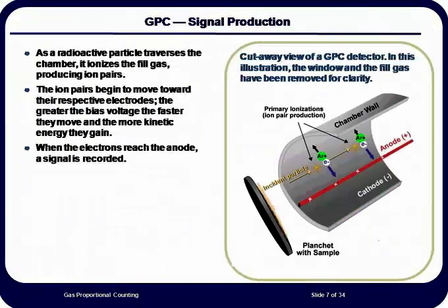In this picture, we see the initial ion pair that is formed within the detector cell. However, here, a bias voltage has been impressed across the cell, and the ion pairs formed will separate and migrate to their respective electrode. The external circuitry of the instrument will allow charges to be collected for a certain migration time, and then cut off any additional charge collection. The total charge collected is temporarily stored in the electronic circuitry and called a pulse. The magnitude of this pulse, called the pulse height, is measured, and one count is stored in system memory in a broad region allocated to either alpha particles or beta particle response.